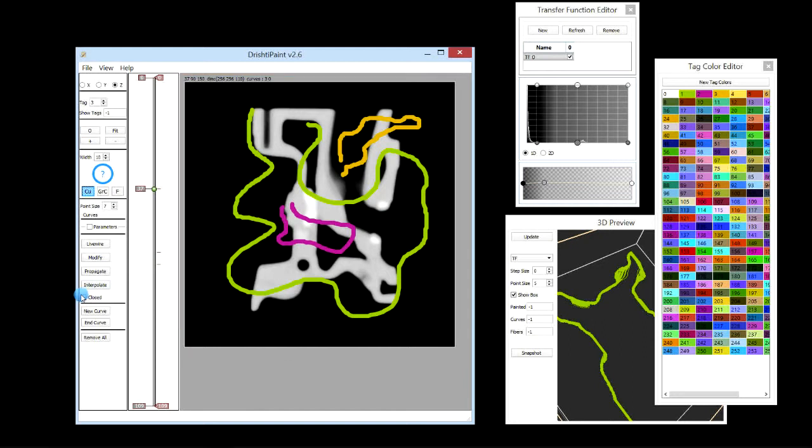Now if you want to have a closed curve, turn on the switch closed, and let's draw a new curve. So I'm pressing A, or you can press end curve and then again new curve, or press A. So I pressed A, and so this one is going to be a closed curve. And then when I press A, this will become a closed curve here. Or when I press end curve, then this will become a closed curve.